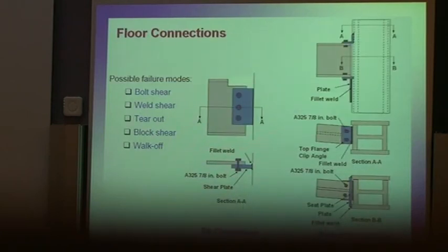Some of the challenges, the biggest challenge actually in this investigation was how to model the connections. Because we learned from the towers too that since we do not design connections for fire effects, especially for shear connections, we design these connections to carry gravity. However, when we have a fire situation, these connections will be subjected to gravity load because that load has to go somewhere, but at the same time there are lateral loads due to, here we focus mainly on thermal expansion.